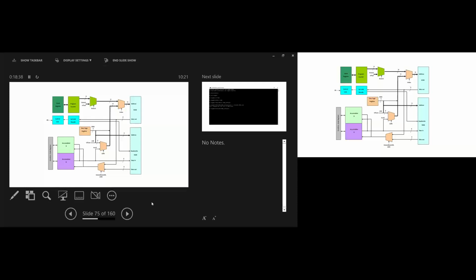Because we designed it ourselves and it was designed a long time ago, it was written in AHDL. Of course, we're using Altera, so we've never bothered to translate it. So one thing I had to do was change it to Verilog. And the other issue that we had was we had an assembler for this. Yes, an assembler, not a C compiler.